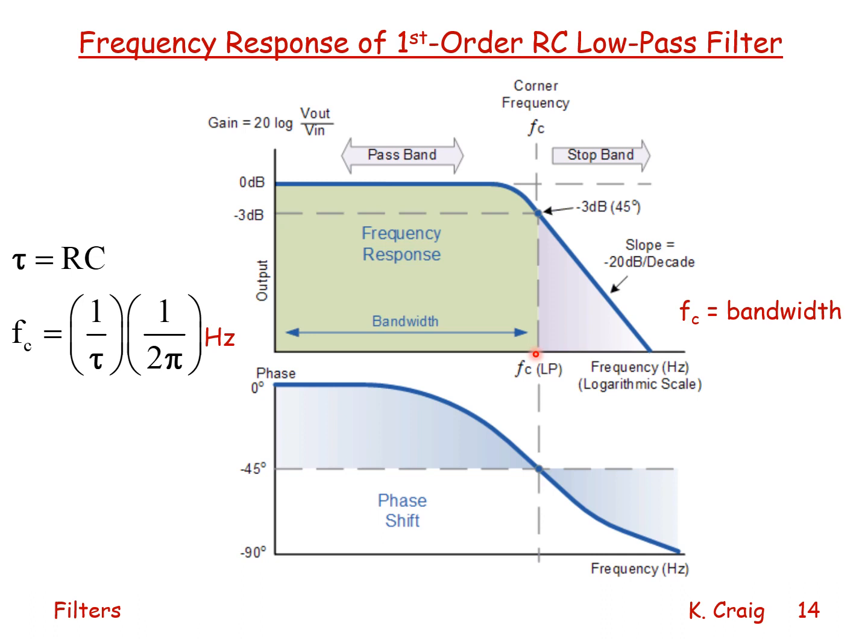If I look at the graph now for phase angle versus frequency, at low frequency, the input sine wave and the steady state output sine wave are in phase, 0 degrees. The phase difference starts to occur immediately as the frequency increases.